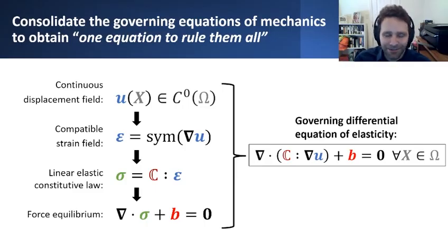That was a requirement that if the body underwent some deformation process, then in order for it to be regarded as a compatible deformation, the resulting deformation didn't result in the body splitting apart at any location. That statement is effectively equivalent to insisting that the function that describes the displacement and how it varies in space has to be a continuous function.